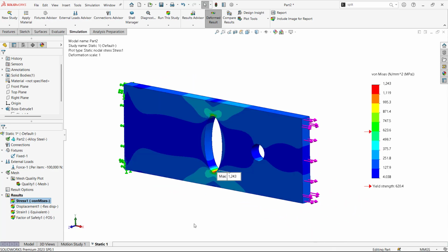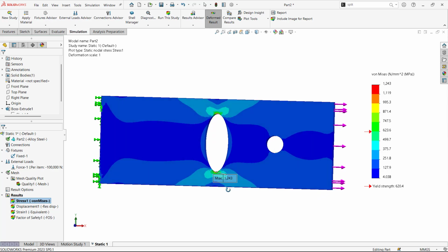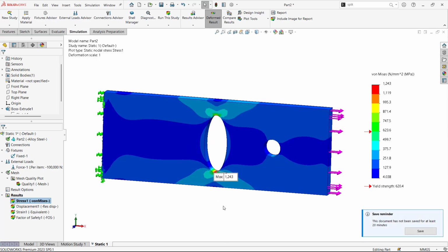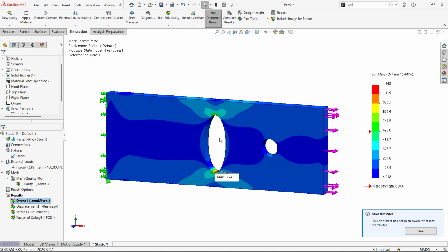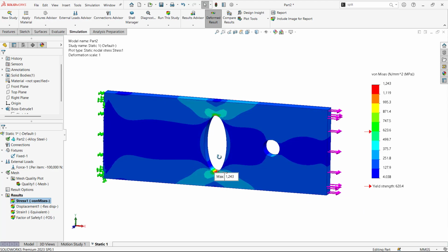Now I hope you understood, right? So how you make your design, and all the things you need to consider in short to make the analysis better. Now see, by just changing the circular shape to elliptical shape, the stress hotspots have drastically increased. The model was performing better, but just a simple design change made my design worse and it is completely failing. So this kind of analysis only you need to do, and you need to tell your counterparts or the vendors. You need to check everything and then tell them this is what is happening.